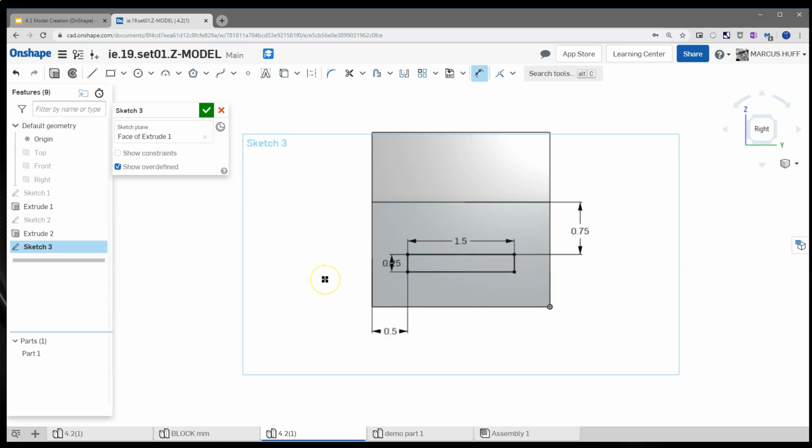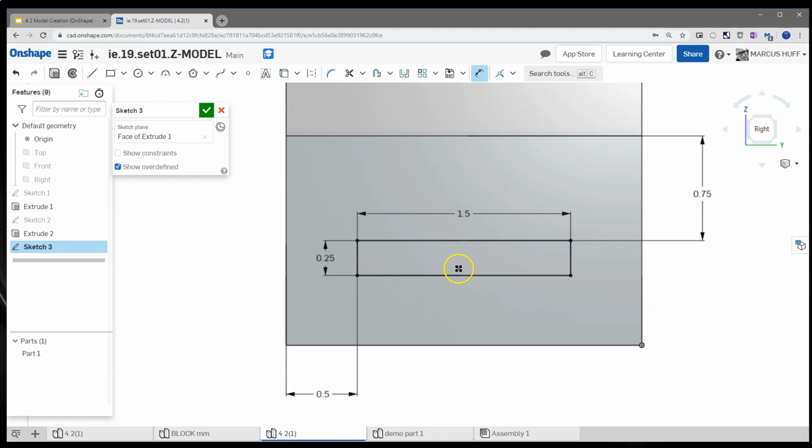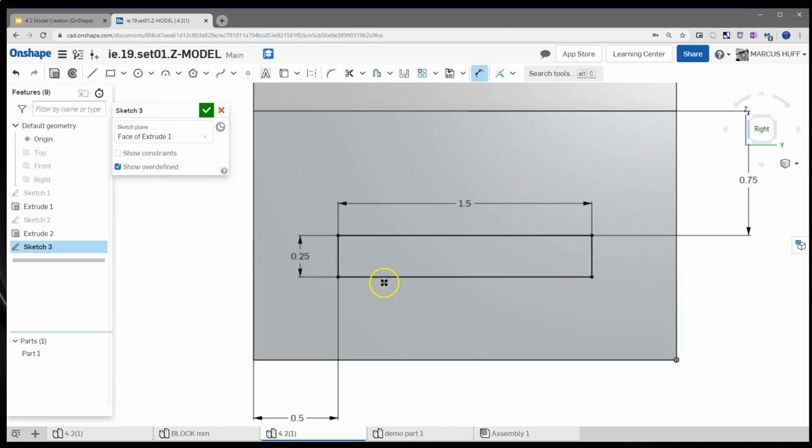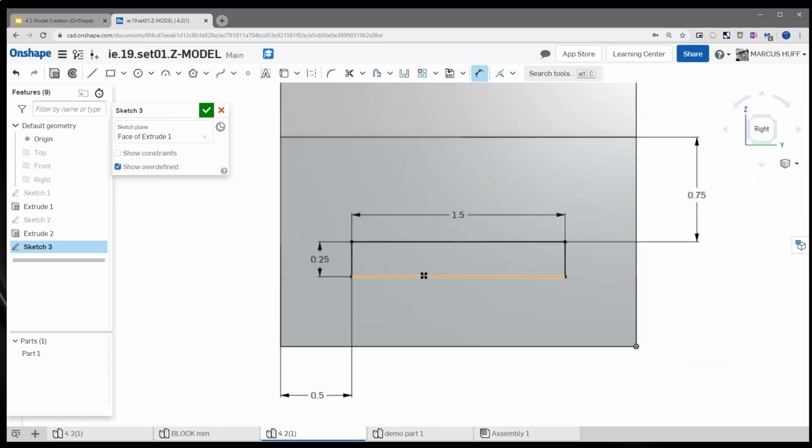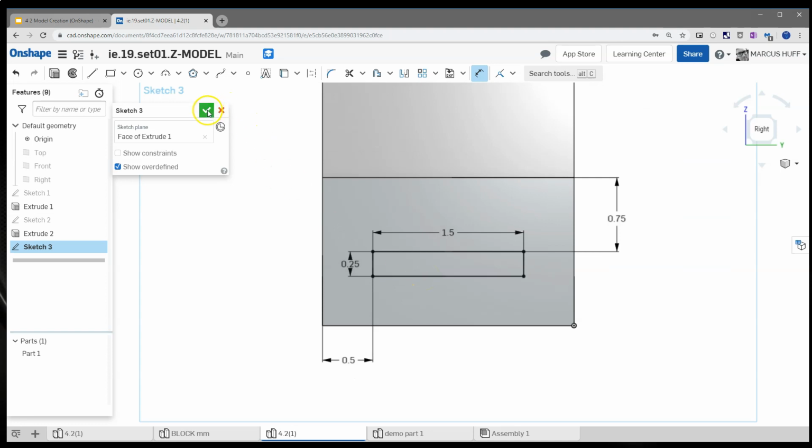It's real important that you make very careful selections when you're doing this. It's real easy to click on midpoints or things that are not what you want to dimension to, so be very, very careful. This is where using your scroll wheel to zoom in will help you see what you're doing with more clarity. Okay, we've got our little object there.